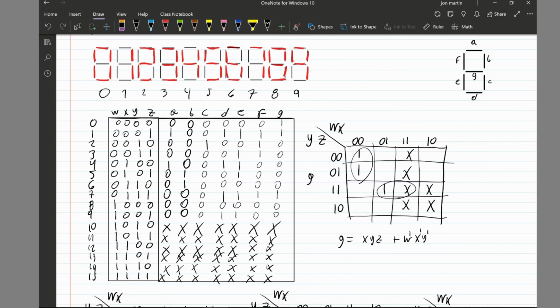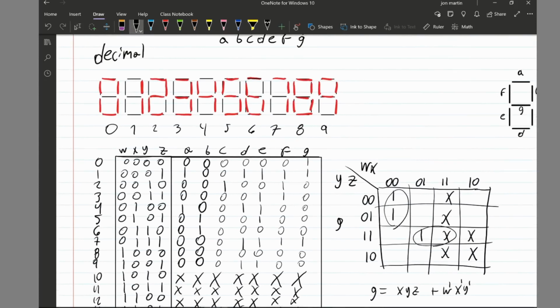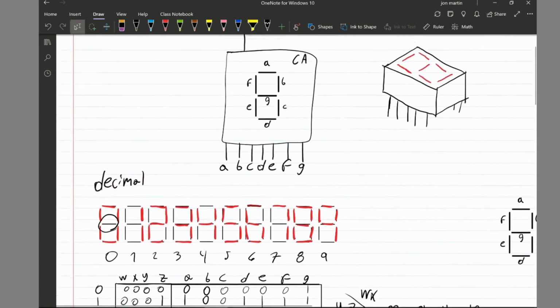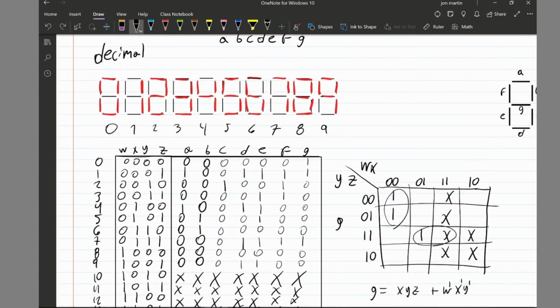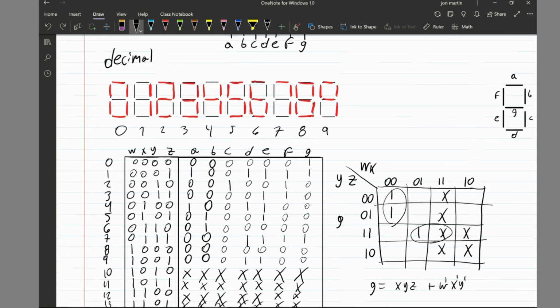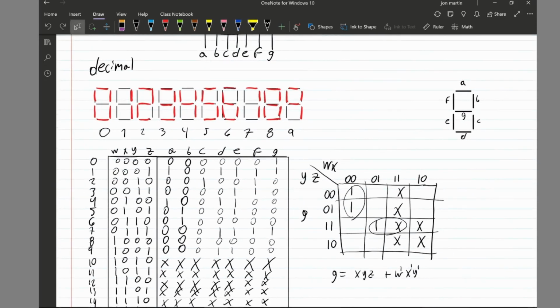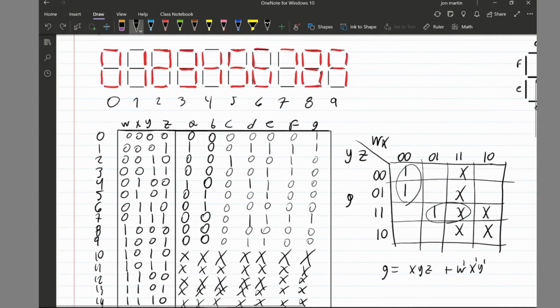If we look quickly at the number 0, if you remember from the hexadecimal video that I posted, we're looking at this line here, and we see that this 0 doesn't have a red line in the middle. So we go to our graph here and we see that G is what we need. We place a 1 on G right here, and you'll notice that the rest are all 0. This is the process we do with the rest of these letters here, and then you'll end up with a table that looks like this. This is the important part of the table.